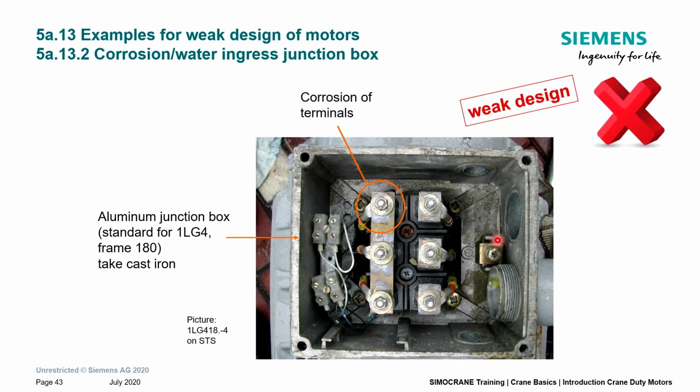What you also should not do is select motors for outside installation, for example, with an aluminum junction box. As I mentioned before, if you have a chemical or salty environment, the terminal box will be gone through corrosion after a short time.